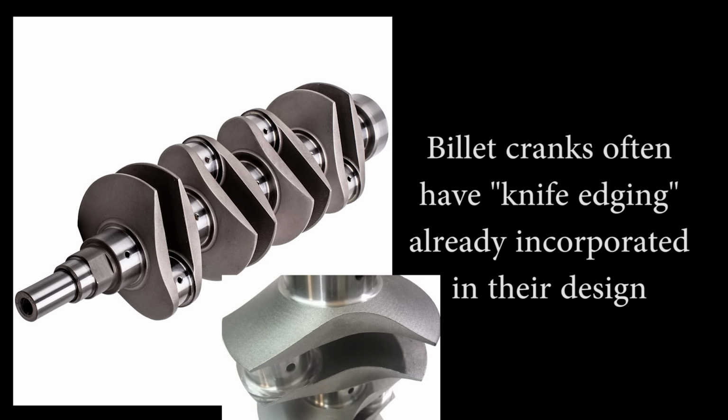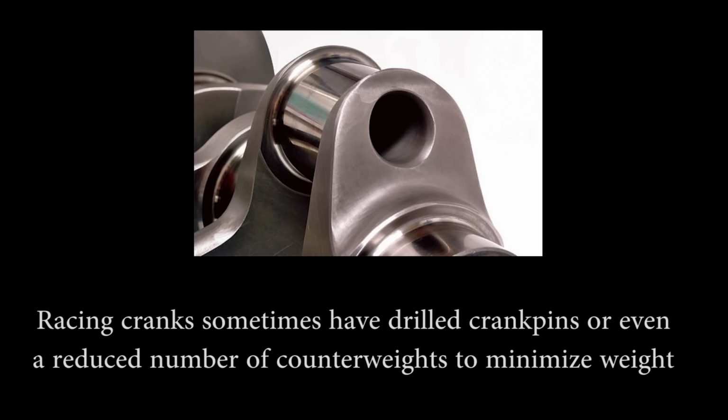Now, racing crankshafts aim to be as light as possible, and this is because lighter engine internals mean a more rev-happy engine and a better throttle response. And this is why you will sometimes see racing crankshafts having drilled crank pins or a reduced number of counterweights.